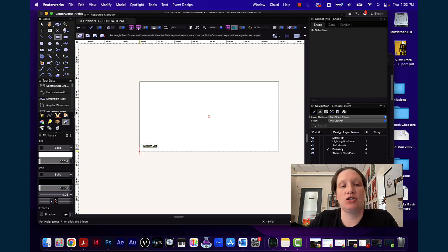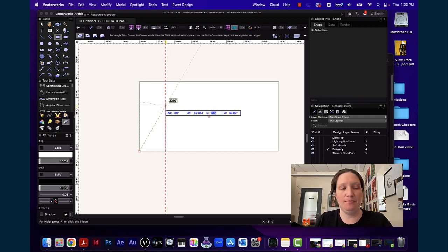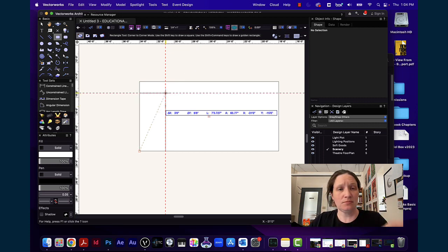Now I want to put a door in her for example reasons, right? I'm going to start down here in the bottom left and create this next rectangle. I know that doors are 3 feet wide and they are 6'8" tall. And I've just gone too far past the Y, so I have to tab my way all the way around again. 6'8" inches. Inches is shift and the close parentheses, right? Because I've had people that just tap the parentheses twice and it does not like that. Now I have this door.